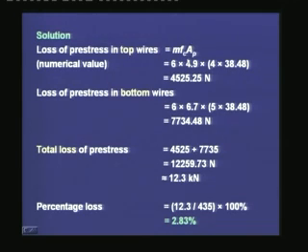That means we are multiplying the drop in the prestress times the area of the prestressing steel to get the total loss in the prestressing force, and substituting the value of the stress at the level of the steel, we get the drop in the prestressing force at the level of the top steel.